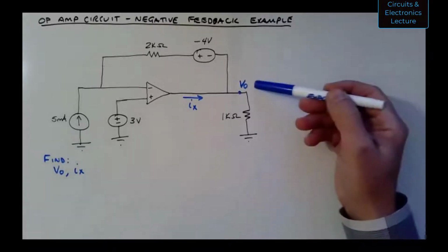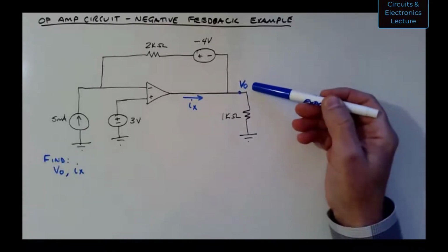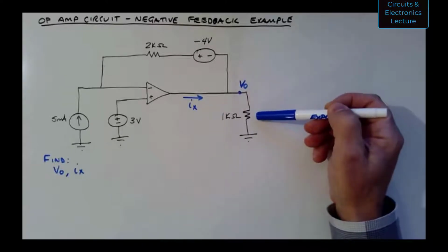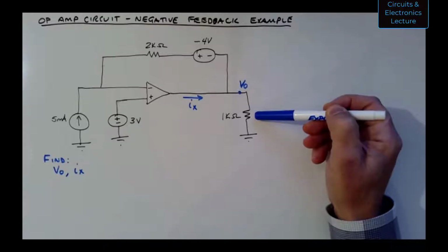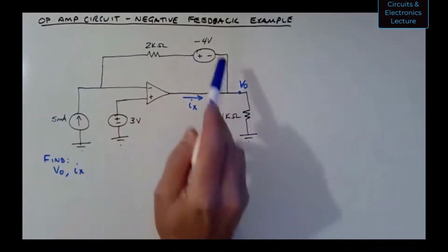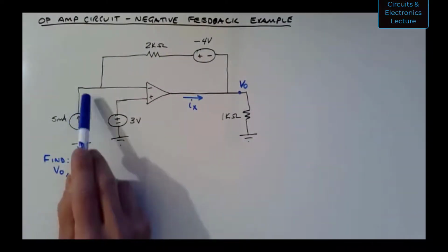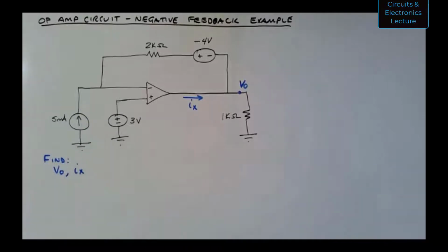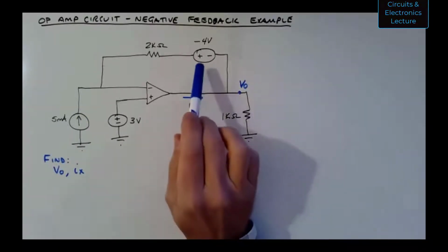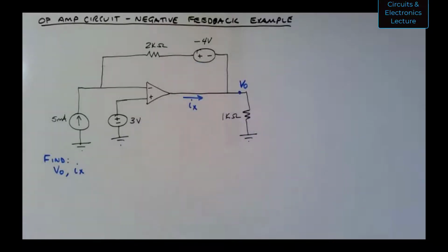So I've defined VO as an output voltage kind of arbitrarily. Let's say that this 1 k ohm resistor is a load resistor, right? So it's just a resistor you connect to the output of this circuit. And this circuit is doing something. I don't have an input drawn here, but maybe the input is like the current into the left side of the circuit. And it's pretty much an academic circuit, especially with this voltage source in the feedback loop here.